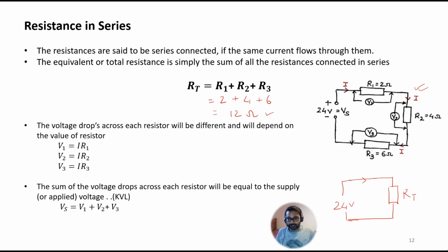Or even while designing a circuit, you may add three different resistances, but it's going to make your circuit a little bigger, right? Obviously we all require a smaller circuit. So while studying your circuit or while designing something, you can reduce it by replacing three resistances with a single resistance with its equivalent value.